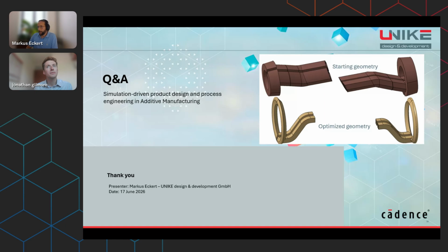As I laid out, one of the hardest tasks for the customer is to articulate the right question. What areas am I really targeting? What is my goal, and what does it mean if I influence neighboring surfaces? And of course, are there any planned machining processes of the part afterwards, which brings me to residual stress, deformation, and deflection?